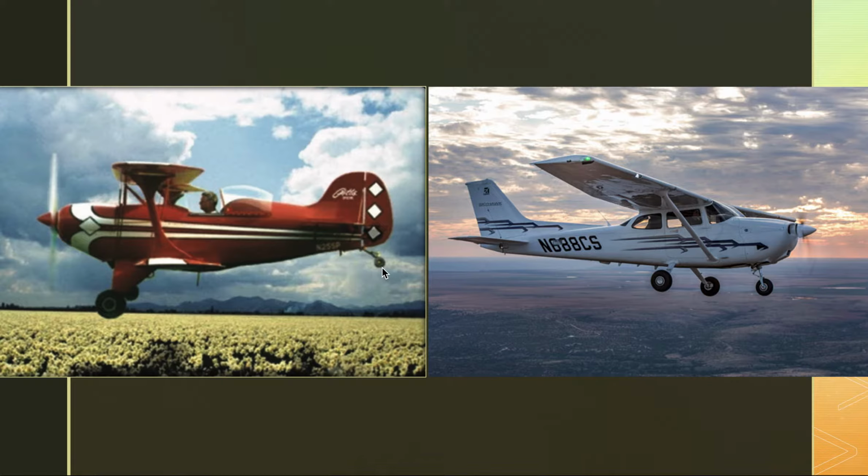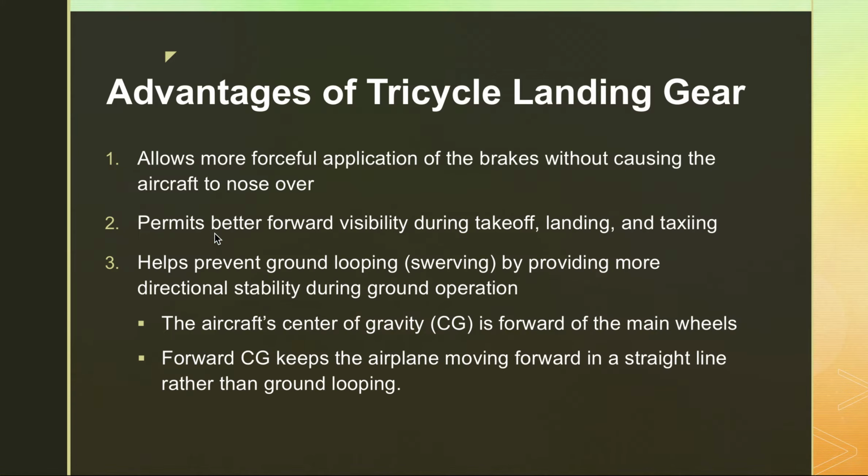Basically, if you land a nose wheel aircraft and you're not quite aligned with the runway, and it decelerates because it kind of lurched onto the runway, the center of gravity being forward of the wheels helps put the nose wheel on the ground and helps keep it pointed where it is. Well, on a tailwheel aircraft, if you land and you're not quite aligned with the runway, then as the aircraft decelerates from that lurching onto the runway, the center of gravity tends to want to go in front of the main wheels. And it does that by turning the aircraft around.